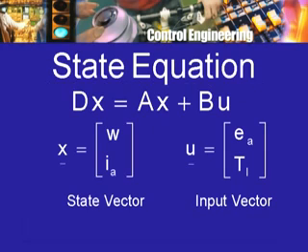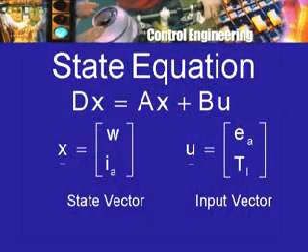So, these are the state equations, or this is the state equation. Now, this is a differential equation. It involves a matrix A and another matrix which happens to be a column vector, that consists of only one column, a column vector B. This is one of the standard forms into which many control system or system equations can be written, and this is called the state variable form. Of course, in this case I have to add they are linear and time invariant, and of course they are ordinary differential equations. All right. So, we have these equations.